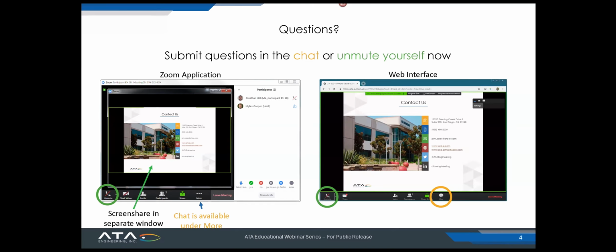We talked about some additional tips and tricks in regards to mid-surfacing, and leveraging your assembly load options within your AFEM to have people working on their sub-FEMs or sub-AFEMs within their own folders. We talked about what happens when you modify a component and how that propagates throughout your entire AFEM, and how easy that is with leveraging your geometry associativity.